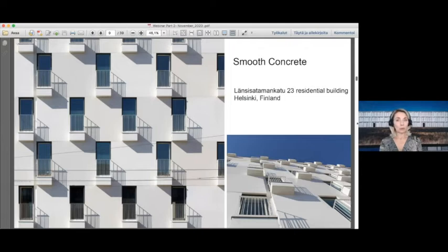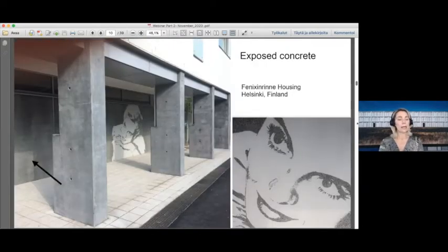Then we have the exposed, or fully exposed, membrane. That's mostly used when you have a graphic concrete image on one panel, like you see here, the lady, and she has a background that is exposed aggregate. Then you have a panel next to that graphic panel that needs kind of the same background. Then it's really important to have the exact same depth of the exposure. So that panel should be made with a fully printed membrane in order to have the exact same tone.